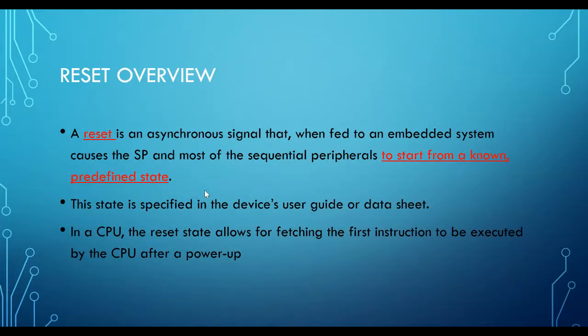Okay, remember what we talked about, the three computational states: fetch, decode, execute. Fetch, decode, execute never stops. It keeps on going as long as there is power applied to this embedded system. Sometimes, in certain circumstances, you need to go to the reset address. Go and look for that particular picture in my lecture slides, where there is a reset and then it goes into the three computational modes: fetch, decode, execute. But it always starts with one reset address. No matter what you program, it will always start from that reset address.